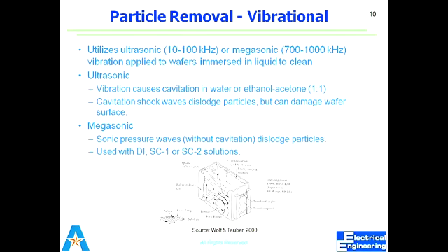It may be DI water, it may be H2O2 or any other liquid. In that liquid we produce those sound waves, and due to those sound waves the cavitation effect comes into account, and the particles on the surface of the wafer get displaced, and because they are moving, it can clean the wafer surface.